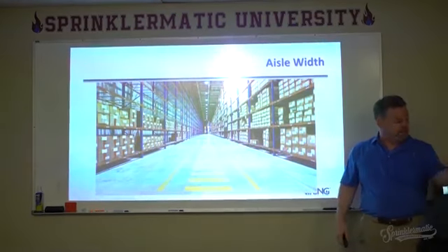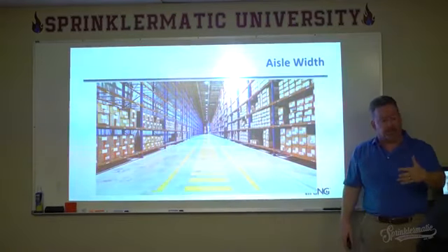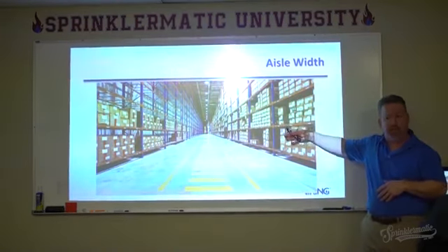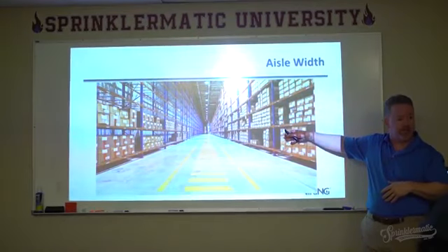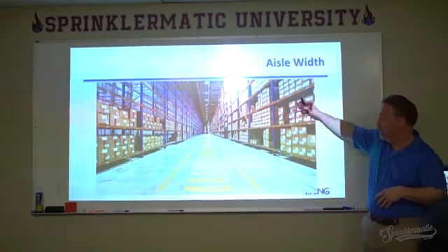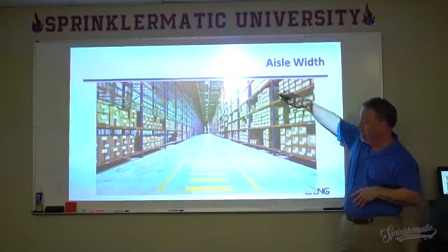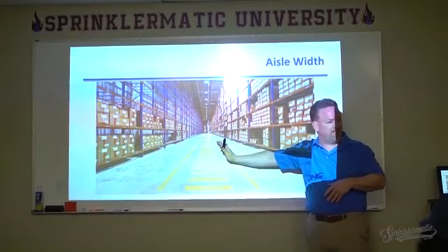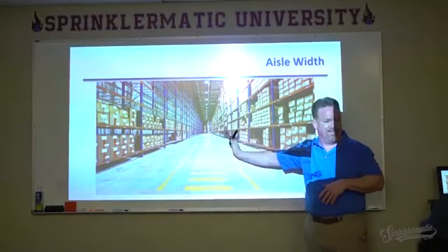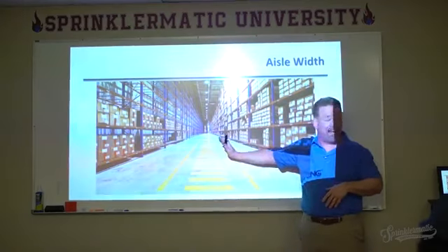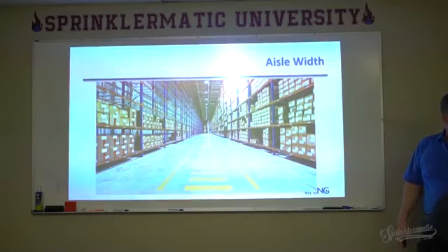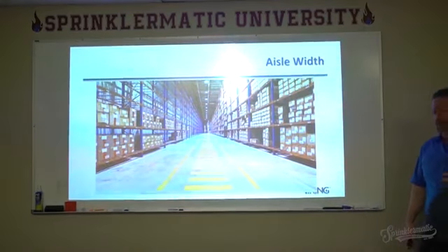That's actually one of the success or failure criteria of a sprinkler system's test when we're designing or testing sprinklers to protect rack storage. We have what we call the commodity that's being tested, and then right over here we got what we call the test array. All right, and one of the things is you cannot let the test array, the exposure, catch on fire, or you fail the test. If it jumps the aisle, you're done. Test failed. Okay.